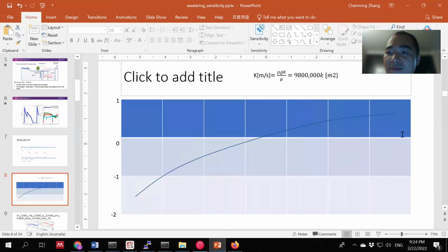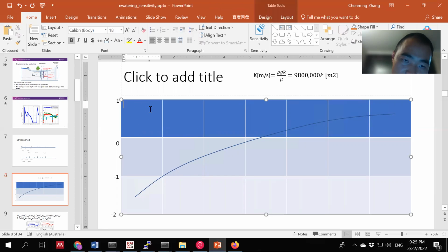We also discussed the three different types of cells within MODFLOW. So this is a vertical 2D domain, and here is the water table. First is the top cell, where the water level is below it. So the cell will be considered inactive. There is a big story about how to convert from dry cells to wet cells that will be covered in our later tutorials.